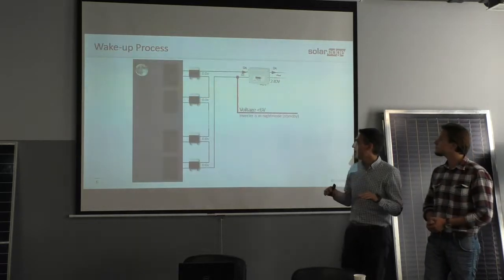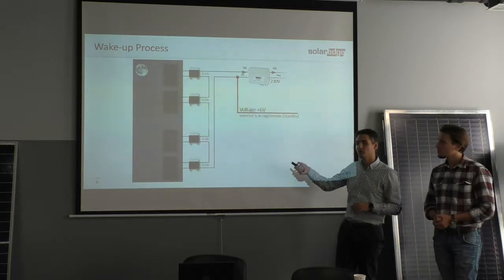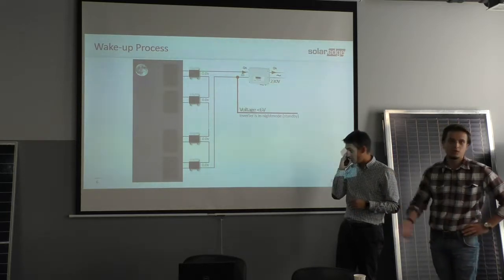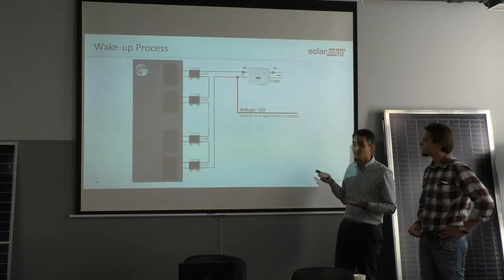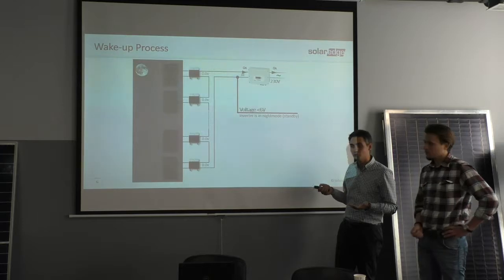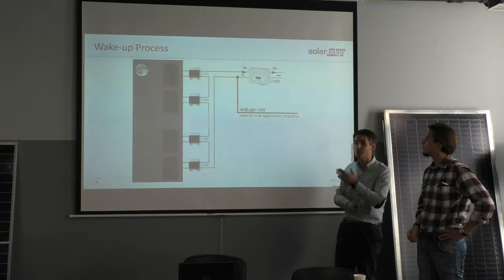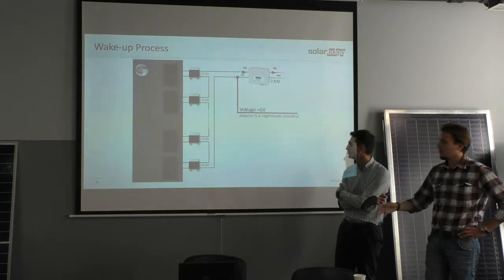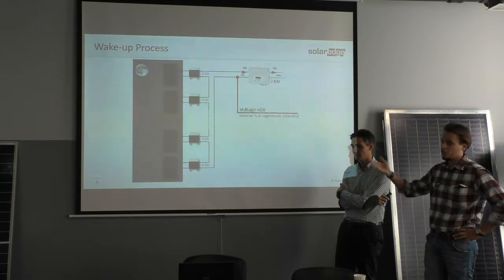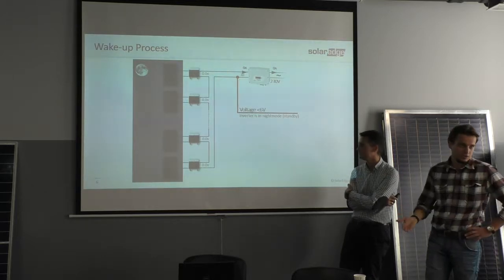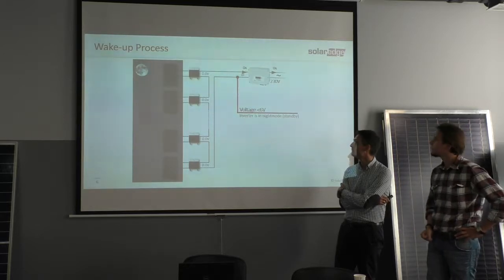Okay, now to understand how our system works at night, when there is no voltage from the modules. So the inverter detects less than 6 volts. In fact, there is zero because no modules produce voltage, so no optimizer gives voltage. It is in standby mode, night mode. As soon as the voltage drops below 6 volts, in fact there won't be any volts at all because it is night, the system goes into night mode automatically.